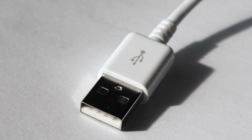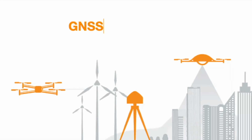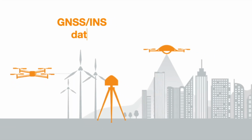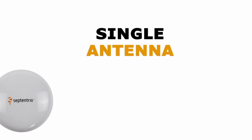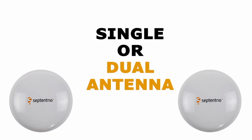The driver supports serial, USB, TCP/IP, and UDP connections, allowing users to utilize GNSS and INS data through both NMEA and SBF, Septentrio Binary Format. It also allows for both single and dual antenna setups for accurate positioning and attitude.